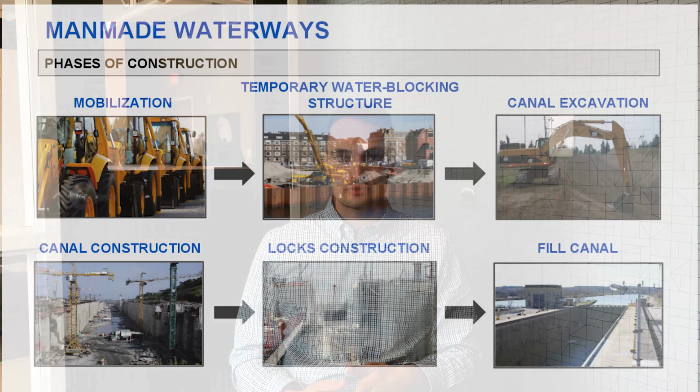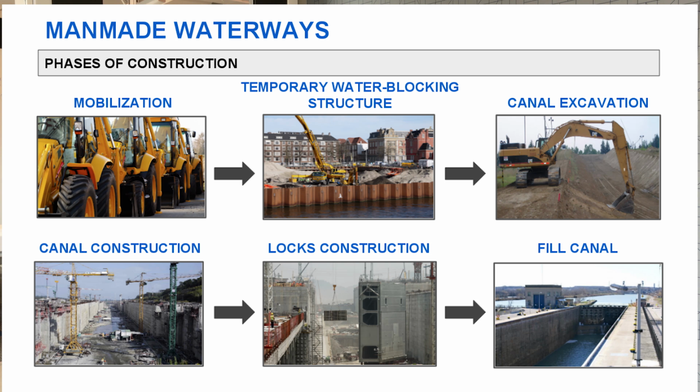Another structure dealing with water is waterways. Waterways are constructed starting with mobilization, then constructing a temporary structure that holds water behind construction, followed up by excavation, constructing of canal walls, constructing of gates and locks, then ending up with filling in the canal with water.